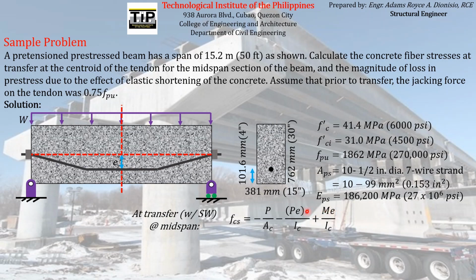fiber that we are concerned with to find the flexural stress, we just have to replace that magnitude c with e, since the distance of the fiber we are considering with respect to the neutral axis or centroid is at a distance e from the neutral axis or the centroid. So we just have to replace it by e. So in this equation, Ac, we can already compute for Ac. We have given cross-sectional dimensions. We can also find the moment of inertia of this particular section because the dimensions are given.